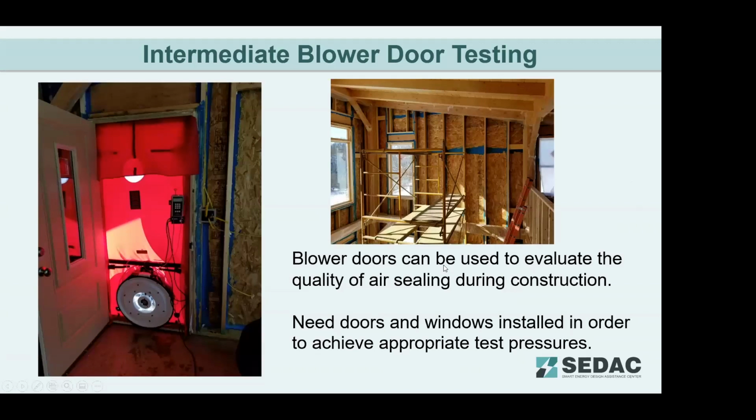Blower doors can also be used during construction. I have done this with some new construction jobs, particularly when I was working with a homeowner who wanted to make sure the building was airtight. So we did blower door testing before any insulation was installed. We needed enough of the envelope closed up, so we needed windows installed. But I've had residential homes with an attached garage where the wall was completely open to the garage, but we had the overhead door in. I say that so that we can get enough of a pressure difference for us to run the test.